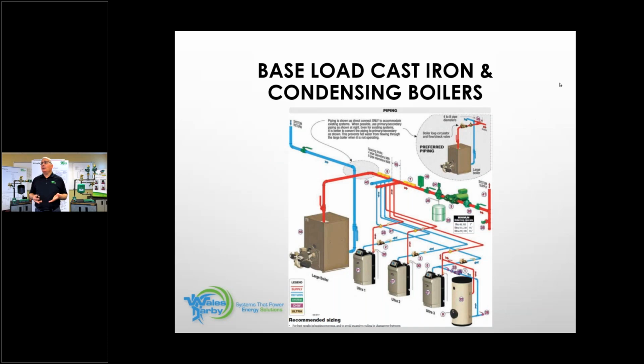I can set them up however we choose based on that manufacturer's control. We'll get nice flow rate across the boilers. We'll get good runtime across the boilers. And if that last cast iron boiler was still viable, leave it on the job, we probably won't have to fire it the majority of the heating season.